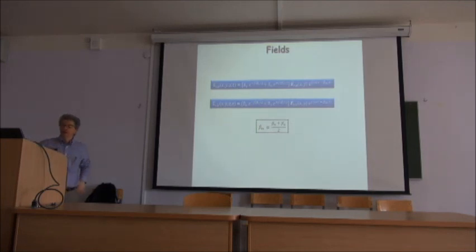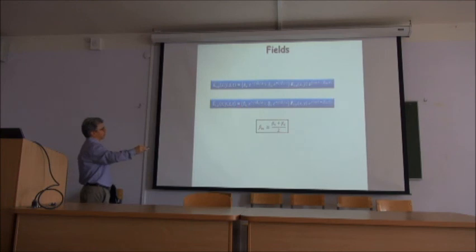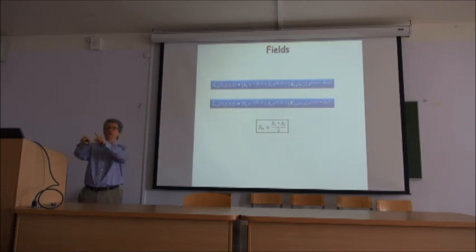Alright, and we can write down the fields now, and I can decompose that in a forward and negative direction there, so I have both present there, and I can do the same for the other mode, and I have split there, and I will also write the Z term here in terms of two components. One that is the midpoint. I have these two betas between those two different modes different, so I'm going to define a new variable that is right the midpoint between them.